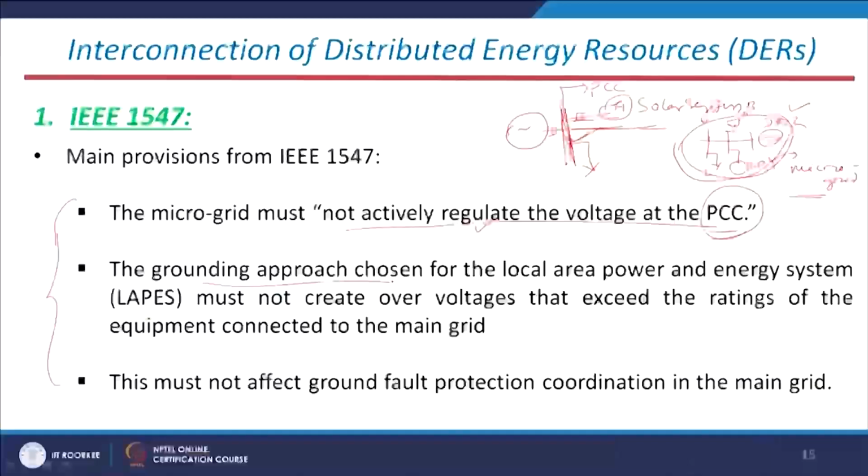And the next one is that the grounding approach should be chosen in such a manner that the local area power system, which stands for LAPS, must not create overvoltages which exceed the ratings of the equipment connected to the main grid.